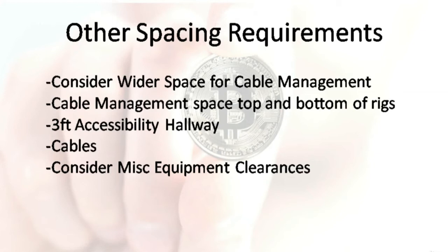Lastly, I wanted to go over other miscellaneous spacing requirements. The standard width of the cabinets is 24 inches, but sometimes you might prefer a wider cabinet solution just so that you can have better cable management. So in that case, I would recommend using 30-inch width cabinets just so that you can manage your cables more effectively. And speaking of cable management, you need spaces between the top and bottom of your rigs for accessibility and, of course, again, cable management.